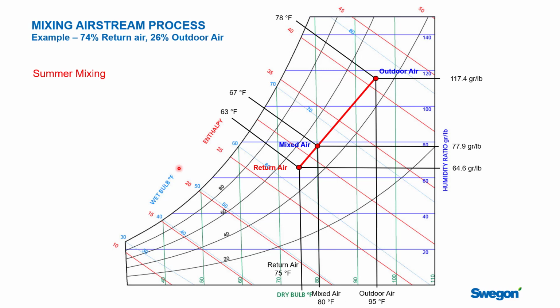Well, I just want to show another common condition. We're still in the summer, and I'm going to use 80/67. If you look up a lot of HVAC equipment that's been tested to an AHRI standard, they have to pick some kind of design condition. If you buy a 10-ton packaged rooftop unit and they say it's 10 tons, 120,000 BTUs per hour of cooling, when you read the selection, it's going to say that was based on a mixed air condition of 80/67.